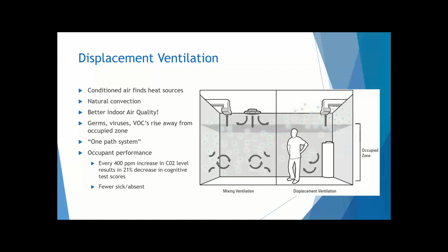So honestly, from what I've heard about reversing the ceiling fan direction, I'd say that if you can, the reason that it's less efficient to do it that way is because you're throwing the air further. So you might not need to throw the air that far to get that heat to the occupied zone. So that's why really there's no reason to go in the reverse direction. You can, especially with the technology we have, not only with VFDs, but EC motors, the modulation of that fan could be turned down enough so that you could reach the floor with that heat, so that you wouldn't need to go reverse at all.